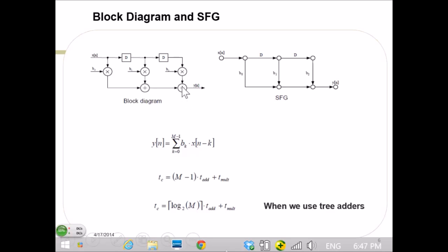Now, the one example I alluded to before was the filter. Say you have this filter equation, which is essentially an FIR filter. You have different samples coming in. Here you have 2 delayed versions of the input sample, then 3 multiplications, and then 2 multiply and accumulates. In terms of the signal flow graph, you can represent it this way. So you have x of n, and we are representing the delay here.